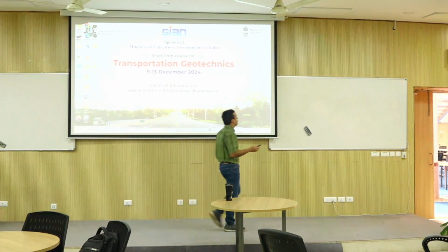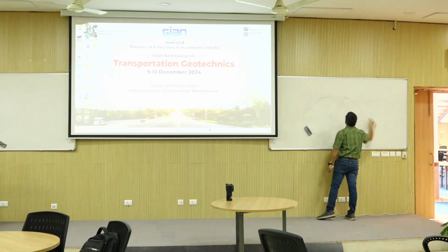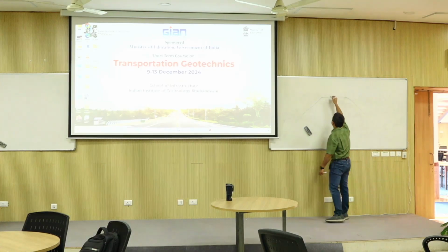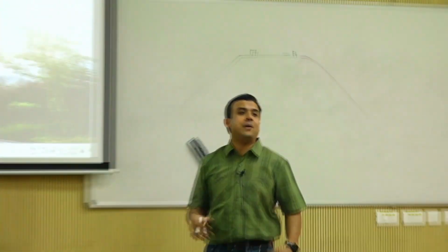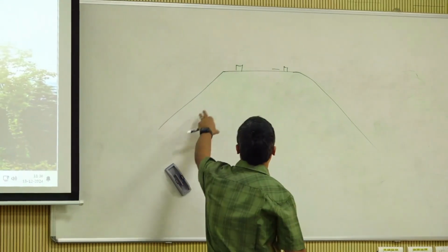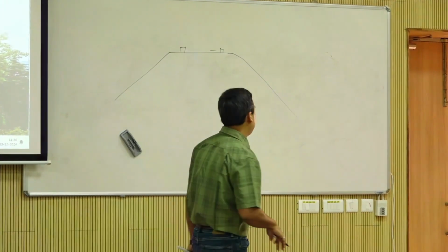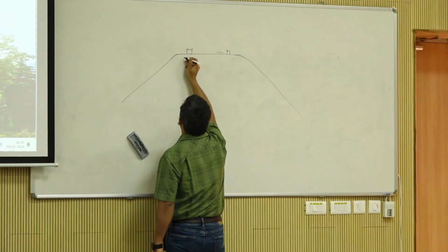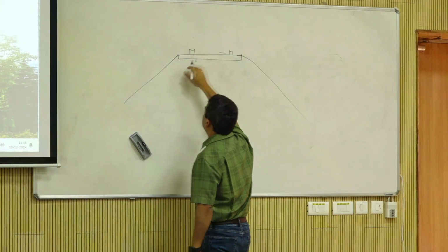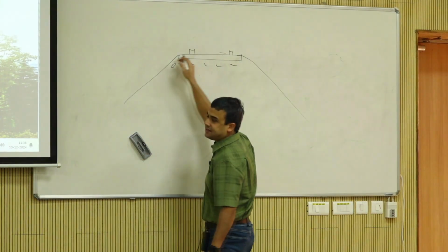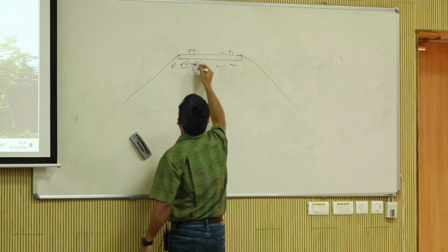If anybody wants to go into some really deep analysis, this is how a typical railroad track looks. The track lies here, and the rails are going that way. This is all ballast, and they have a shoulder, with certain specifications for how to do shoulders. I'm sure Indian specifications have that as well. The problem is when you have your cross ties here, this is a tie, let's say, and ballast all over, and then it rains, or it starts getting fouled. So there are a lot of areas here that are fouled.